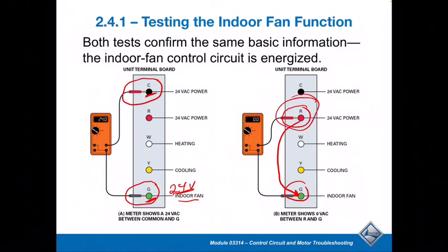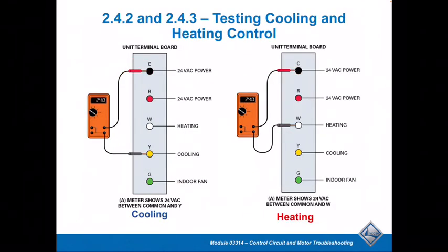So if you're going to do that test, you probably want to check your voltage between the red, or the 24 volt hot R terminal, and the common to see, do I really have voltage here? Then, if you go between the red and the G, if it is indeed calling, you would expect 0 on that meter. If you read 24 volts on that meter when you go between R and G, that would tell you that circuit is actually open, because there's a potential difference on there. So those are the things you have to look at.